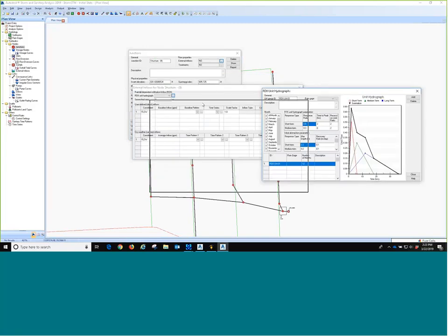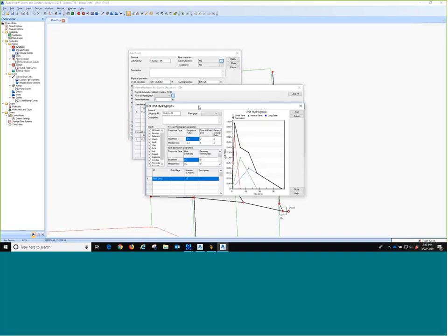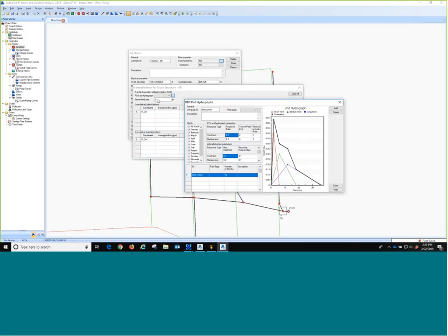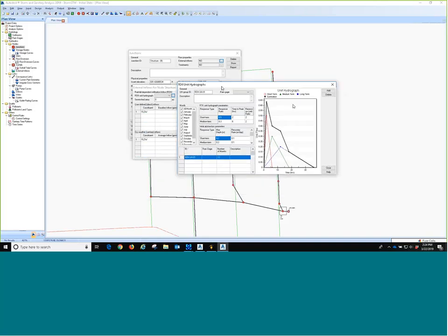So if you're doing a sanitary sewer overflow analysis, you already have flow meters in place, and you have your hydrographs in place, I could place them in here and set my sewer shed area, and it would run based on the time frame that I've given it. I'm not going to get to that level in this presentation, so I'm not going to be using these, but I just want you to be aware that that is where they are.